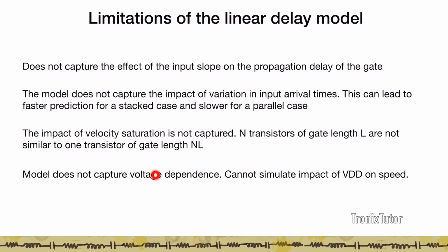And finally, the model does not capture voltage dependence. VDD is a very important parameter. It's an important knob that we generally use when we want to improve the performance of a block, and that is something that cannot be captured by this linear delay model.